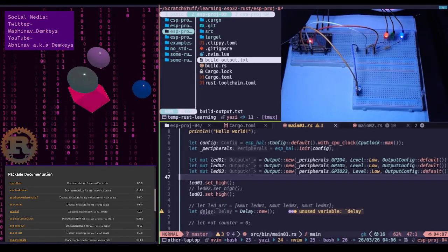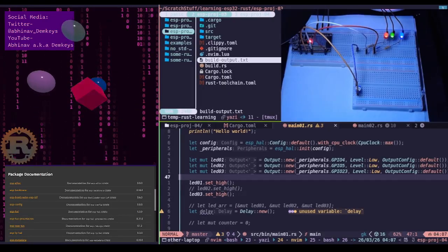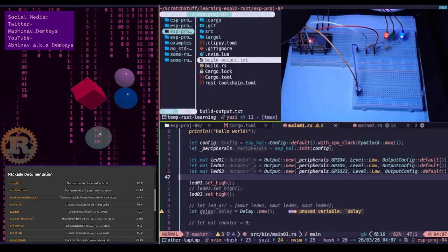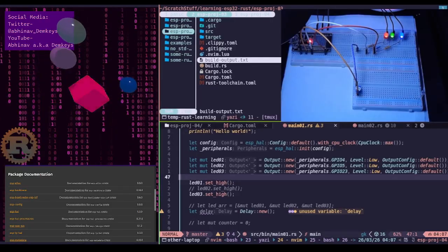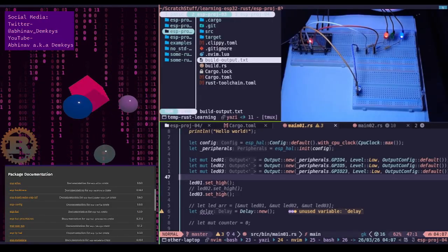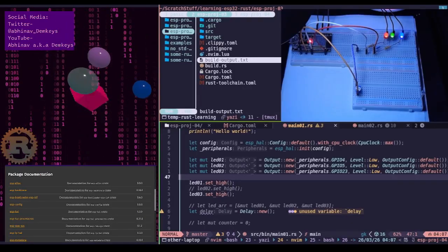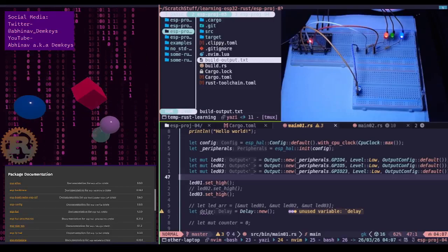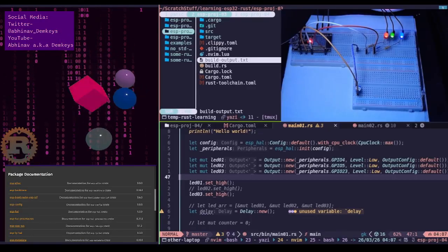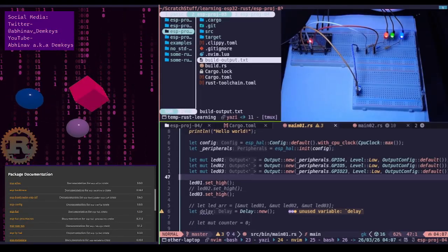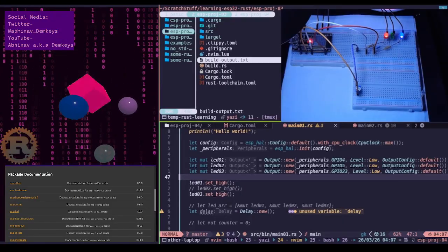Basically, the more light you give it, the lower its resistance is, and the less light it receives, the higher its resistance is going to be. And apparently, its resistance is usually in the mega ohms. I don't know how much this specific one is, but at least according to Gemini, it's in the mega ohms. In my case, if it happens to be in the kilo ohms range, or hundreds of kilo ohms, that's still perfectly fine for me.